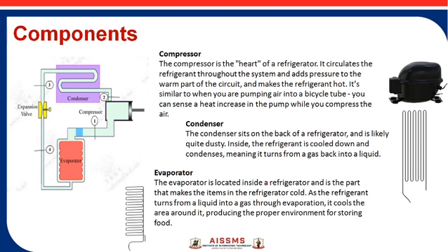Now we'll see the components of the refrigerator in detail. The compressor is the heart of the refrigerator. It circulates refrigerant throughout the system, adds pressure to the warm part of the circuit and makes the refrigerant hot. It is similar to when you are pumping air into a bicycle tube. You can sense the heat increase in the pump while you compress the air.